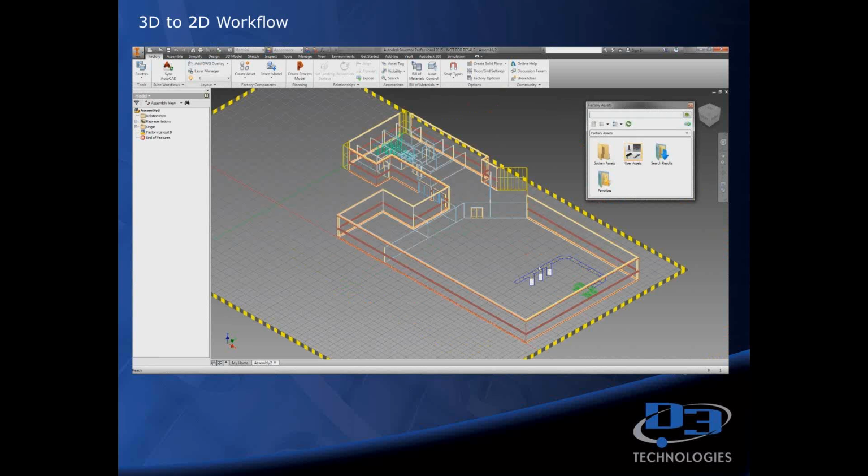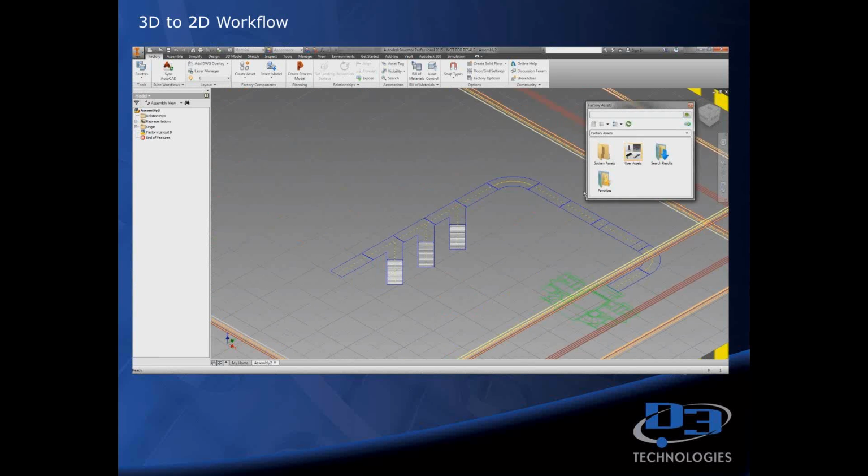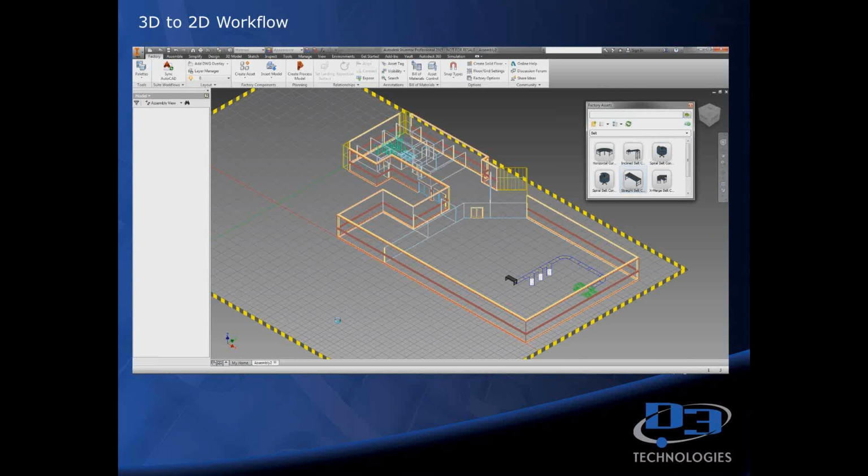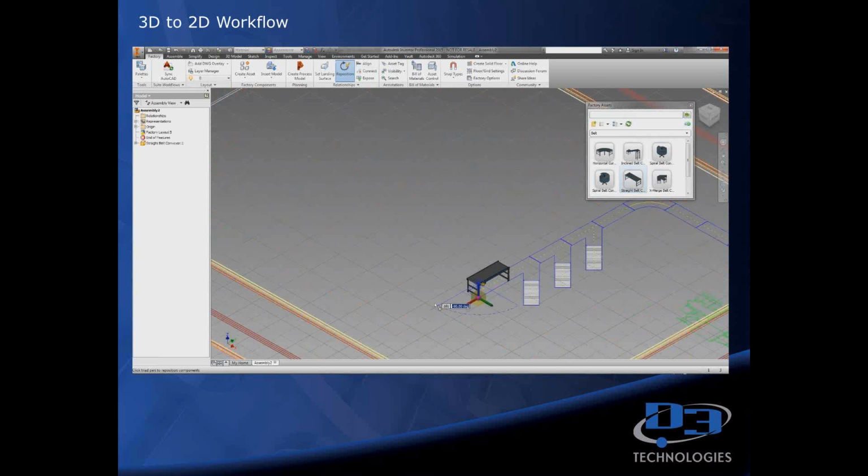As you can see, I've got my 3D representations of the walls as defined in architecture, and then I also have these 2D placeholders for my 3D objects. So coming over here to the assets, again, I'm coming into the conveyors, and this time I'm going to grab the 3D model straight conveyor. Now when this asset was published, it was published with defined insertion points. So I can use those insertion points in the model and actually snap to the 2D layout that I had connected to this assembly. So I'm just going to set the orientation here and place that factory asset.